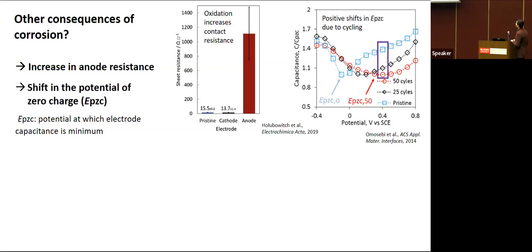So you can see that for the blue profile before operation, the capacitance is about 1.4 times greater than the capacitance of the electrode after operation. So due to cycling, we are basically losing some capacitance of the electrodes to remove charged species. As a result, you remember that decline in salt removal over time. That's due to losing the capacitance of the electrode over time and due to corrosion of carbon.